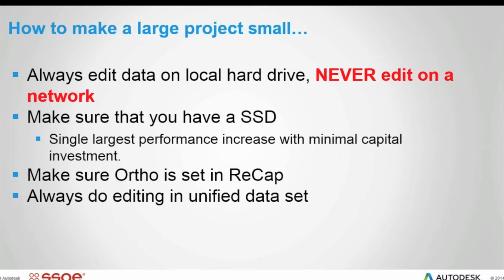Then I reunified the data. So I took all those RCSs, unified them as one. That took like 35 minutes to run. Once it was unified as a single RCS file, and then I did an export of only the floor feature, it took another 35 minutes. So in an hour, I was done. The other one I had to wait 2 days. So that's the key there, is making sure that you have a single RCS file from a technical perspective.